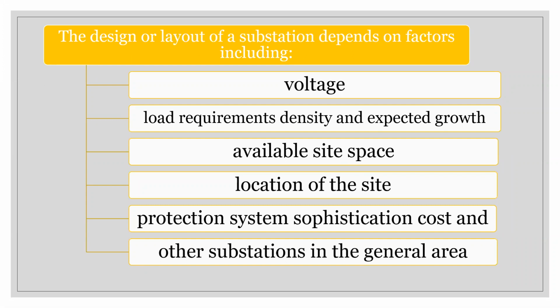And also, the design of your power system will have to give consideration to other substations with which it will be connected. All right? So there's an interconnection, for example, between Upper Camp, Hope, and they are the primary substations going into the university hospital. But in terms of operation, it is such that if one fails, the other one will continue to supply the hospital.